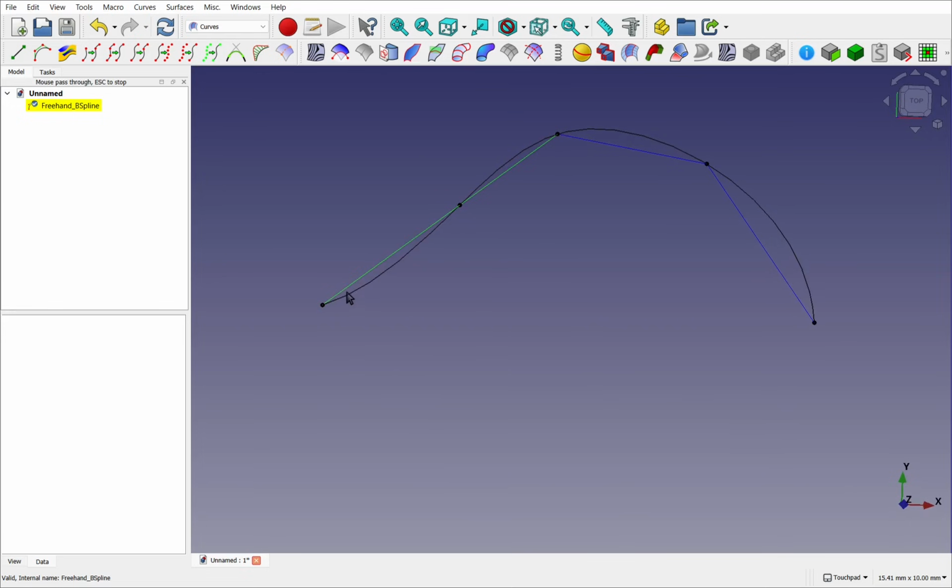So those segments are aligned now. But we're still keeping the curvature. So remembering we're looking at the top plane, make sure we're on the top plane. I move this curvature over here and selecting these two, let go of the control key and just hit P on the keyboard. That aligns those two now. Remember, if we move, we break that alignment, hit P, and now click to accept. So you can see that there. Those are aligned and we've got that curvature.